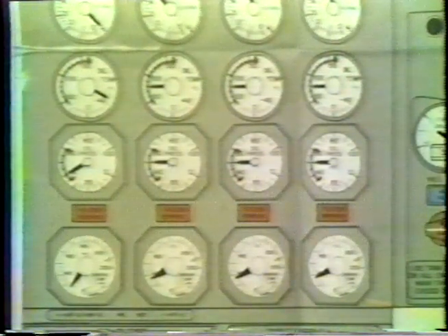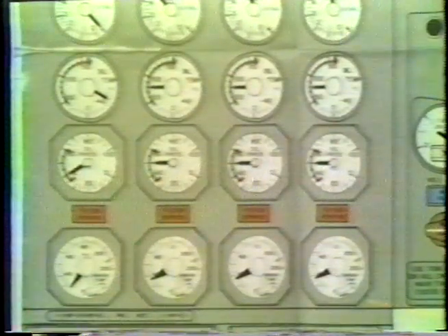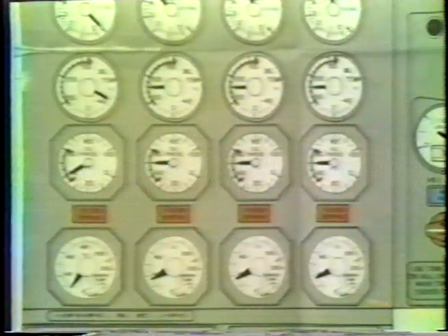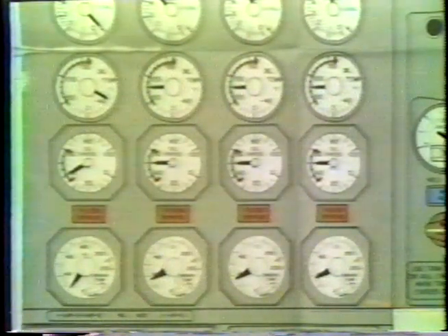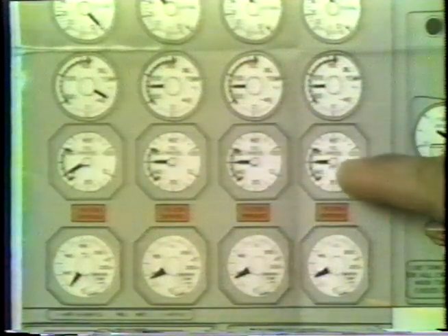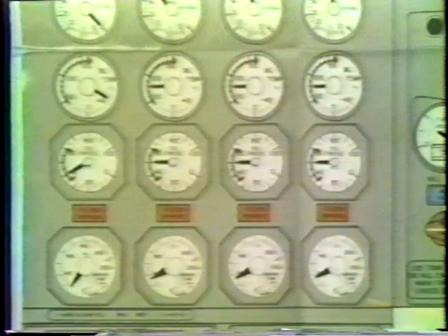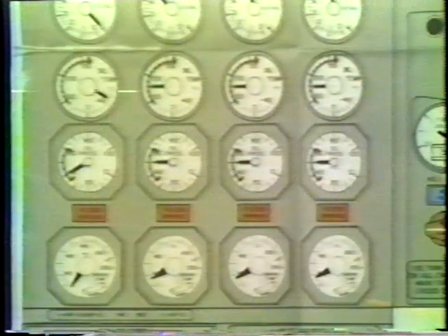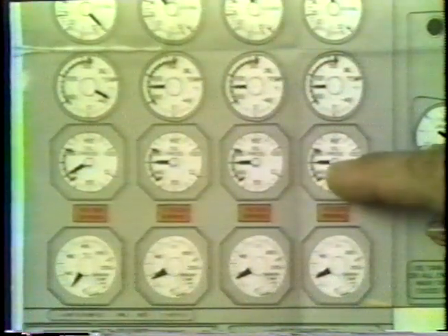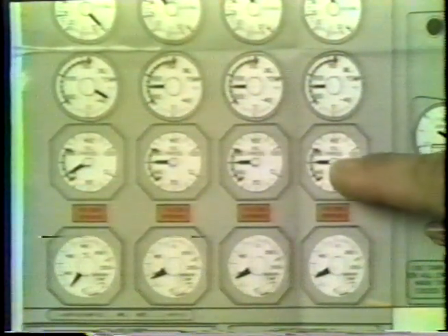In association with the oil pressure gauge, there is an oil pressure light on the front instrument panel. These two sensors require different power supplies, so the loss of one will not affect the other. One of the problems involved with the oil pressure gauge is with a gauge failure, the pointer will remain in position. So it's difficult to tell whether the oil pressure is proper or not. However, if the oil pressure light up front is on with the pressure in the green band on the gauge, an engine shutdown should be considered.